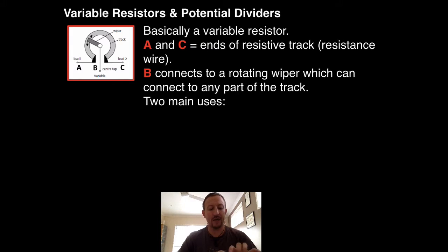A rheostat consists of a large lump of coil. Current comes in on one side, it goes through the coil, and then you'll have a spreader bar at the top, which will allow you to determine how far along the wire your current is going to go before it comes out and goes into your next appliance. Now, basically, if you look at the diagram here, current enters through A, it will then go round the loop and then come out at B, and it can go all the way through and come out at C if we wished it to.